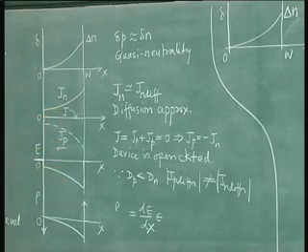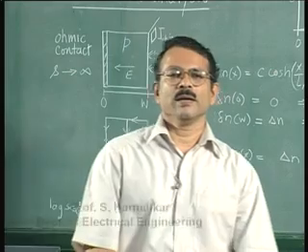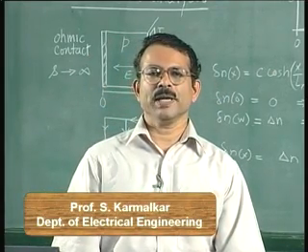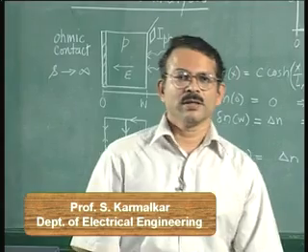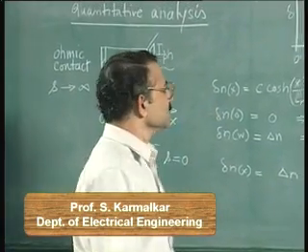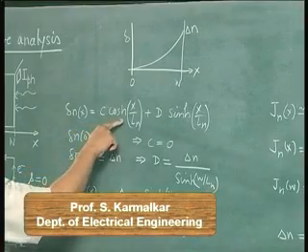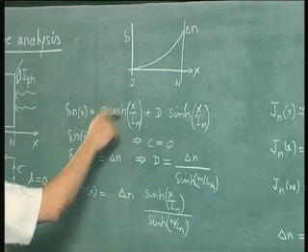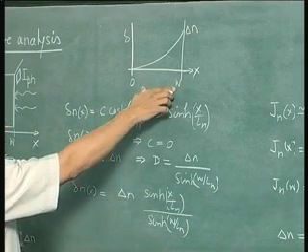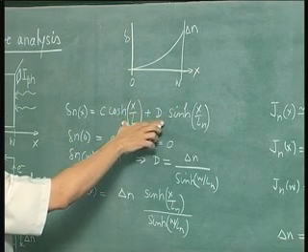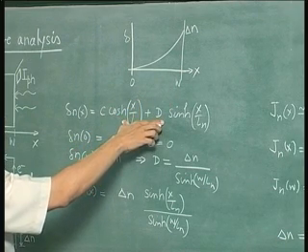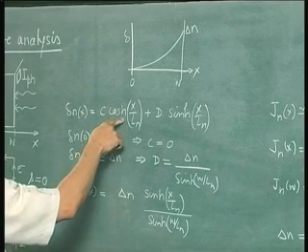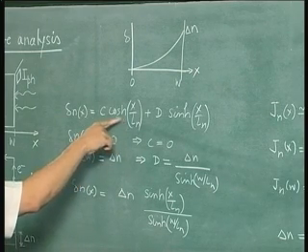So this we will do next. Now the excess carrier distribution obtained from the diffusion equation, that is the starting point of quantitative analysis. We use the hyperbolic form of the solution of the diffusion equation because the sample is finite. We have explained why for a finite sample a hyperbolic form of equation is more suitable, and it will also become clear in this analysis how the hyperbolic form is more suitable.